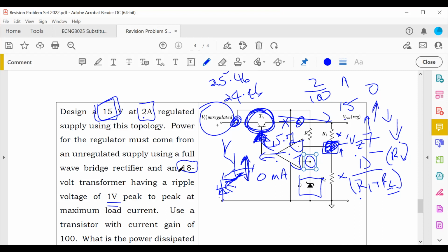It will start to shut itself down. And you put something like a 3 amp fuse, so that if all else fails and the current goes above 3 amps, then the fuse will blow and the thing will shut off. Yeah, so always put a fuse, no matter what electronic circuit you're designing, always put a fuse on the input of the system. So you limit in the event of worst case short circuits or anything, the fuse will blow. That's guaranteed to eliminate any fire hazard because of something overloaded.